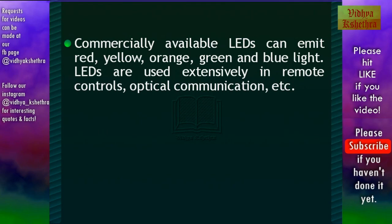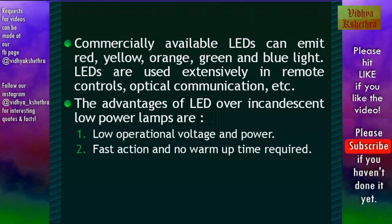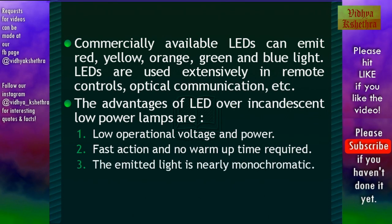Commercially available LEDs can emit red, yellow, orange, green and blue light. And the color depends on the band gap of the semiconductor material used to make the LED. LEDs are used extensively in remote controls, optical communication, etc. The advantages of LEDs over incandescent low power lamps are low operational voltage and power, fast action and no warm-up time required. The emitted light is nearly monochromatic, and they have long life and ruggedness.